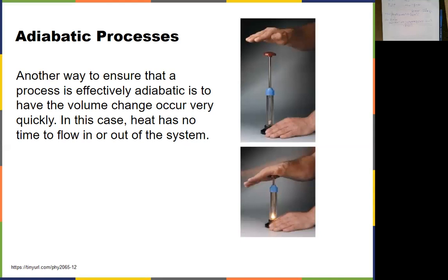So ΔE is proportional to the temperature of the gas. So in that sense, if ΔE increases, the temperature inside increases quickly, okay? And if you are doing this quickly enough, you may reach the ignition point of the tissue paper. So then you will set that on fire, okay? For diesel engines, actually, it doesn't have an ignition like a spark plug. It actually uses this mechanism, that the process happens quickly, so then it can ignite the diesel gas in the chamber, all right?